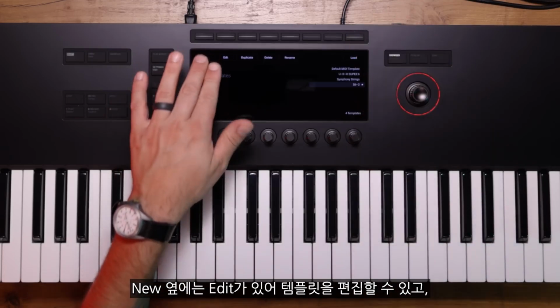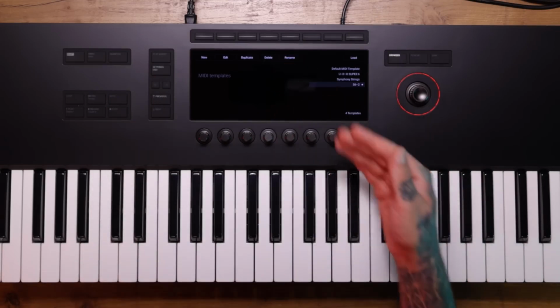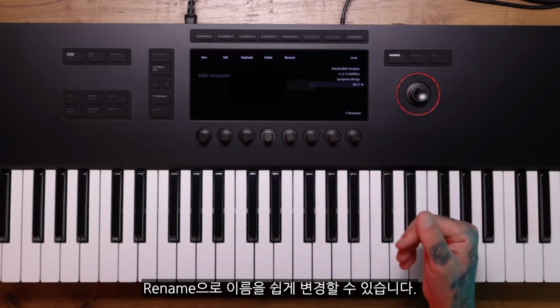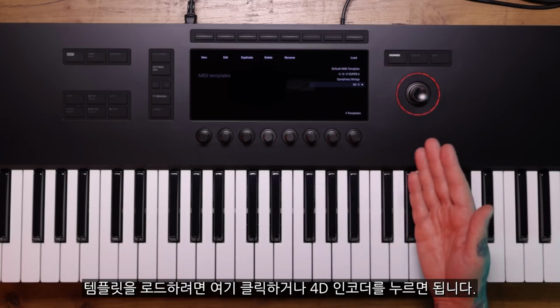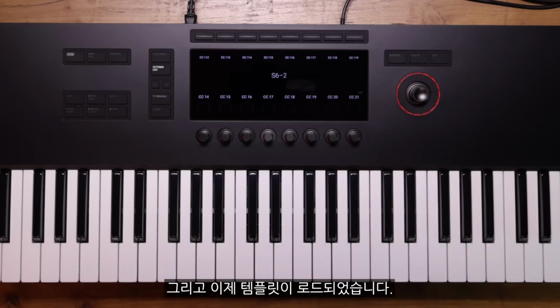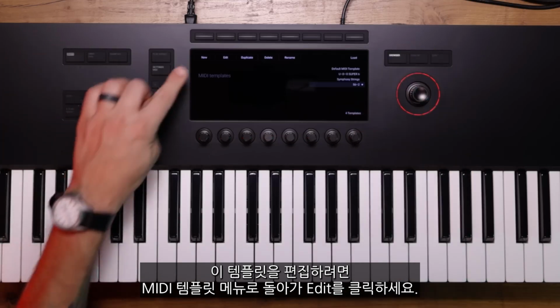Next to New, we have Edit, which allows us to edit our template, Duplicate, so you can duplicate your templates, Delete, which will delete it from your list, Rename, which is super convenient, and Load. If you want to load a template, you can either click here or push on the 4D encoder. And now our template's loaded. If we want to edit this template, we're going to go back to our MIDI template menu and click Edit.